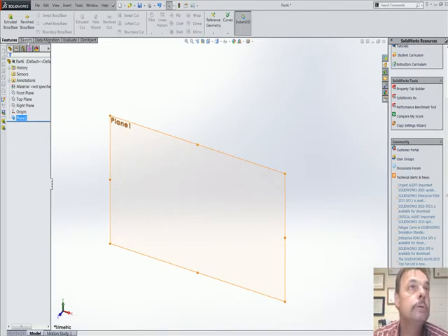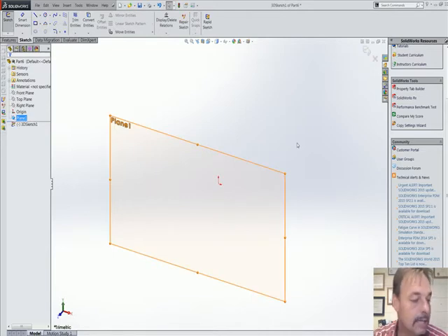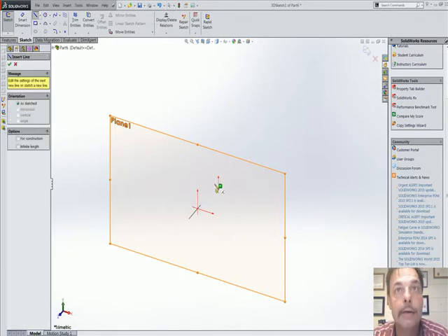Now let's go to, I believe it tells us to go to 3D Sketch. Okay. Now what 3D Sketch allows us to do is sketch in X, Y, Z coordinates. Right now you can see that Z's towards me, Y's up, and X of course is horizontal. So what we want to do is hit the tab button twice. 1, 2. Once we invoke the line command, sorry.